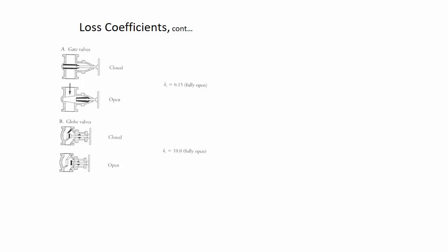But I think probably what would make it harder to open and close is more often just going to be corrosion and rust and friction in the handle and the rotating assembly in the threads, rather than the hydrostatic forces that are pushing on the gate. Oh, okay. But the main concern with the globe valve is just that it has a really efficient seal.